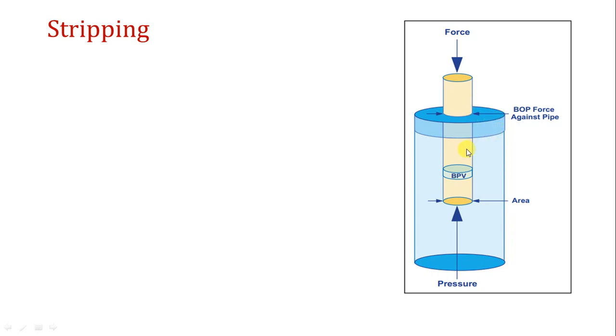Okay, so how can you run in hole? You cannot run in hole with this type because there is a pressure from below. So what do we do? We add some sub. It's called the full opening safety valve, it is put here, okay, and then closed.